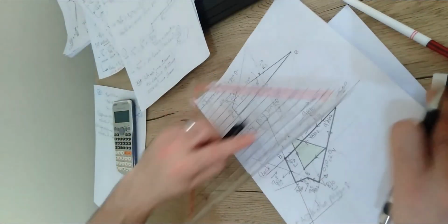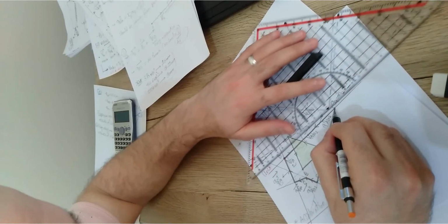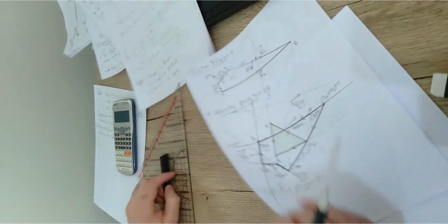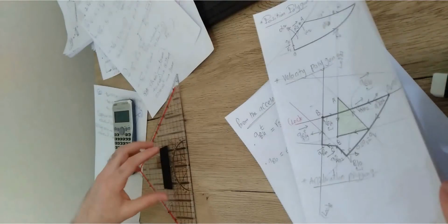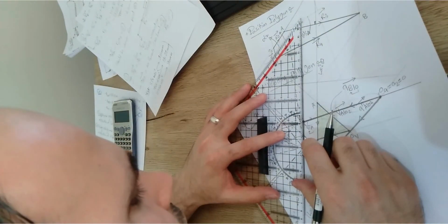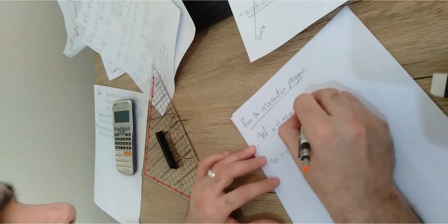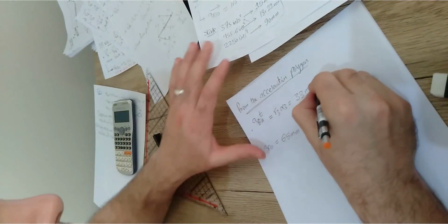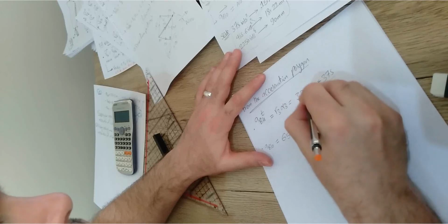So going back here, the B relative to O, which should be the distance between B and O. If you just measure this length, we're going to get it as like 65. So this value is 65 millimeter on the graph, so it should be scaled back. Also the A tangential, it should be this value, which is going to be like 33 millimeter. So this value should be scaled back. So we're going to multiply this 33 by 375 divided by 15.